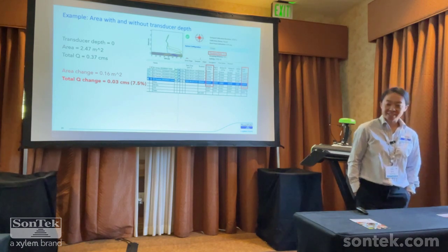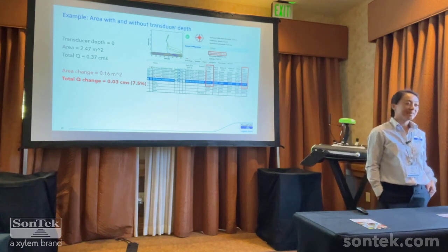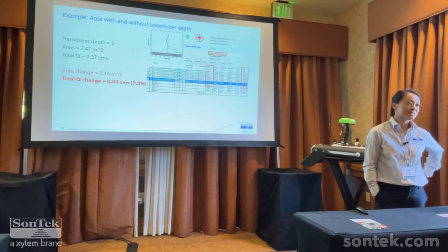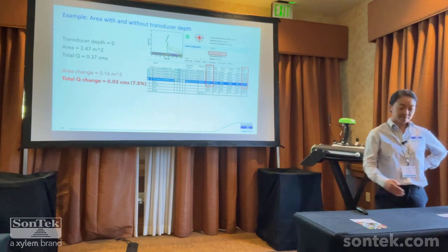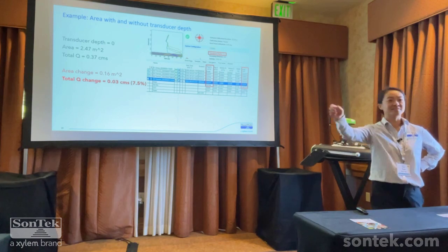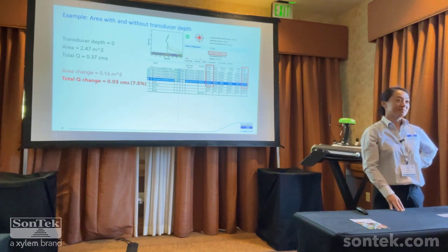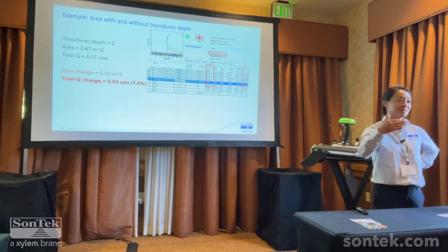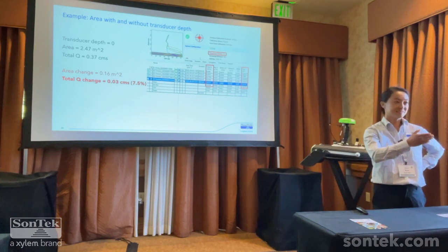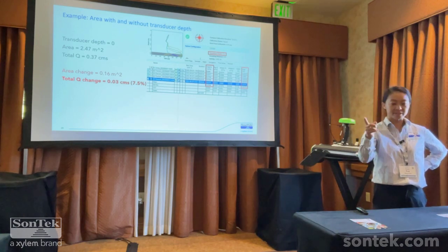So generally, when you have situations like that, it is helpful to use a stationary method, just because then you're not required to do a smooth transect across. If you've got stuff coming down from upstream, then you can avoid those by just picking your stations and not having to go across smoothly.